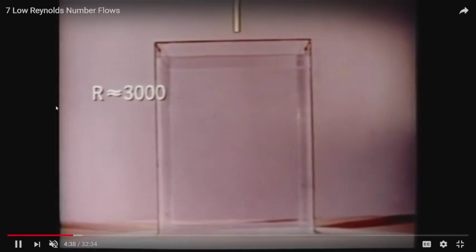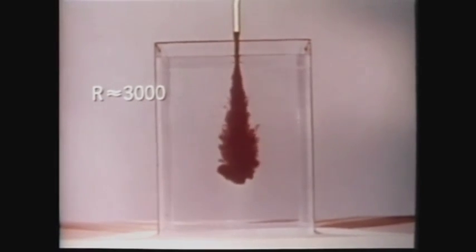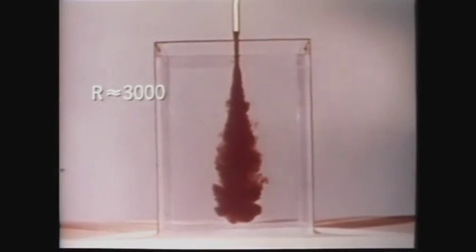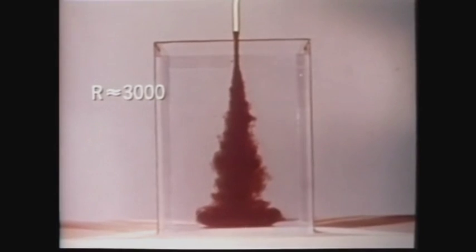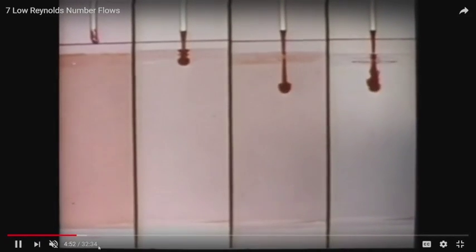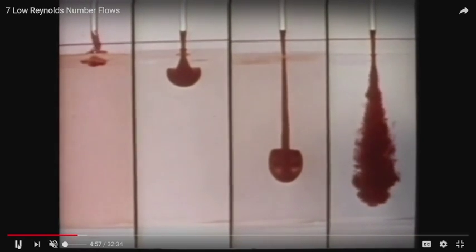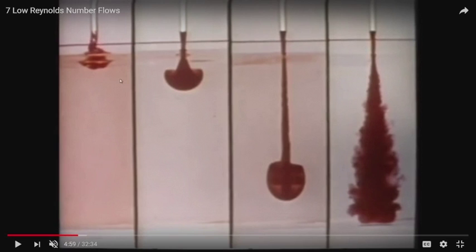And this is a Reynolds number of 3000, and you can tell that there's substantial mixing going on. So this is a comparison between mixing in turbulent flow and mixing in laminar flow, and why it's very important to understand your process physics. Right. Stop right there. No mixing here, very poor mixing here, and here, very excellent mixing in turbulent flow. 0.05 Reynolds number, I think this was 10, this was 200, and this was 3000.